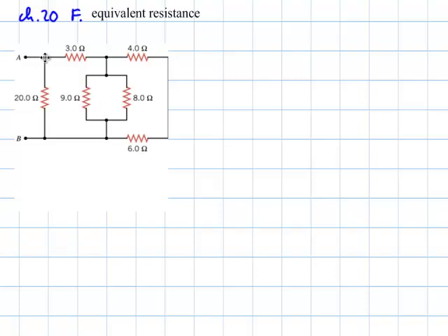The electric current goes in here. Here's a junction. So it goes through here. I need to click on that. It splits up here, and it splits up there, which means whatever comes after that must be in parallel with this one. So all of the stuff here on the right hand side can be considered in parallel with this one. In fact, the current flows through here, flows through here, flows through here, comes back to this junction here where it rejoins the other part of the current that it split up from, and then comes back to be the same current. So this resistor is in parallel with everything else.